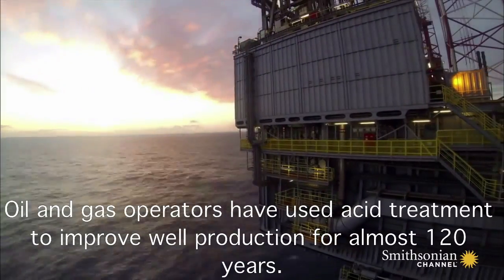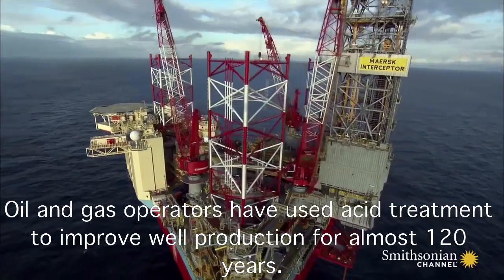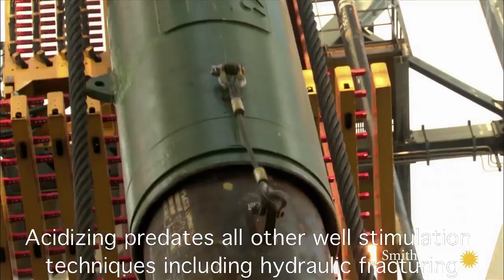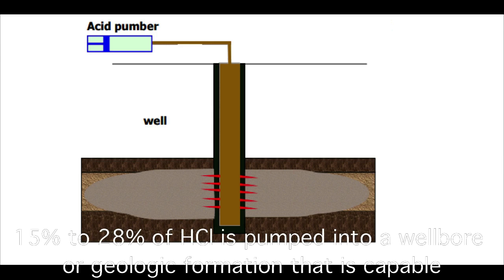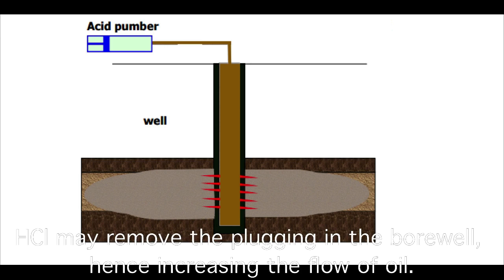Oil and gas operators have used acid treatment to improve well production for almost 120 years. Acidizing predates all other well stimulation techniques, including hydraulic fracturing, which was not developed until the late 1940s. 15% to 28% of hydrochloric acid is pumped into a wellbore or geologic formation that is capable of producing oil and gas. Hydrochloric acid may remove the plugging in the borewell, hence increasing the flow of the oil.